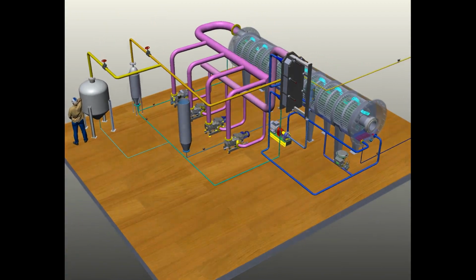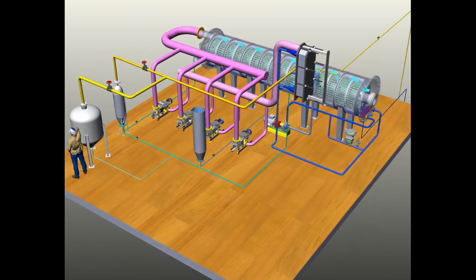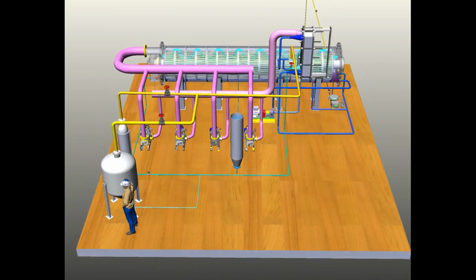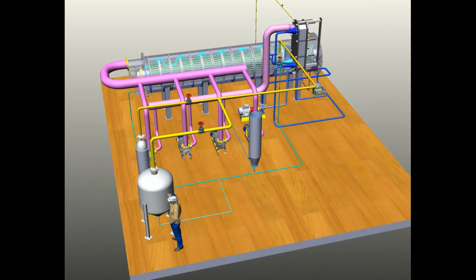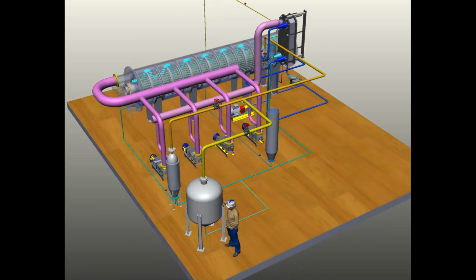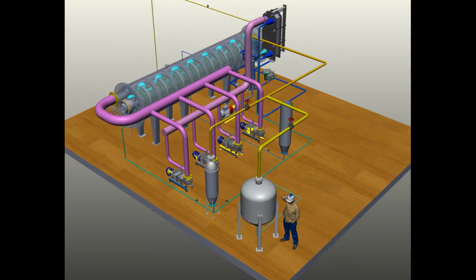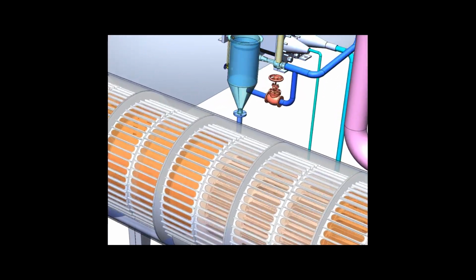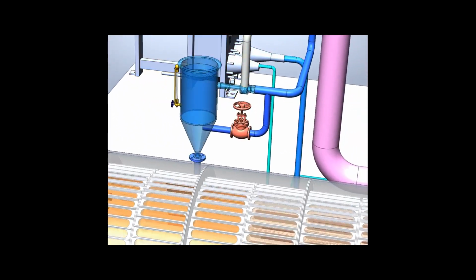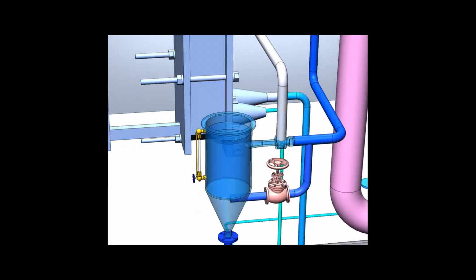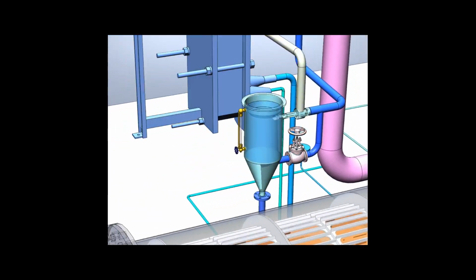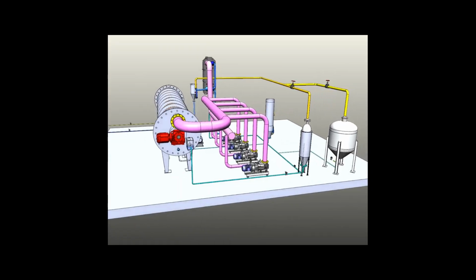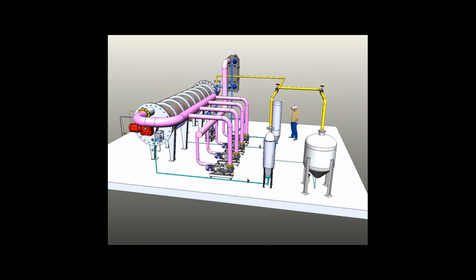In addition to the mass transfer apparatus in which steam is generated, the plant includes vacuum pumps, a heat exchanger, a coolant circulating circuit, a circulation pump, shut-off and control valves, capacitive equipment and an ejector. An ejector located at the inlet to the volume compensator of the coolant circulation circuit ensures the creation of a low pressure at the outlet of vacuum pumps of about 3 kilopascals, which create a vacuum in the mass exchanger from 400 to 700 pascals.